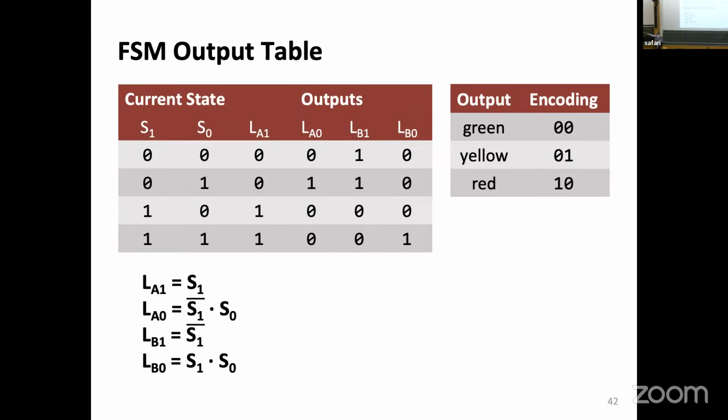Instead of clearly separating, this part of the code does the next state logic, this part does the output logic, this part does the state register, they tend to bunch everything together. That's when mistakes happen and life gets complicated. It still works, it's just more difficult. Questions so far?